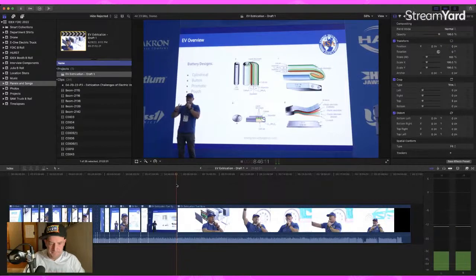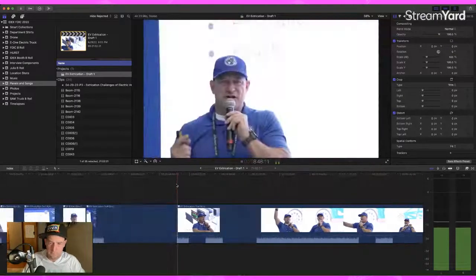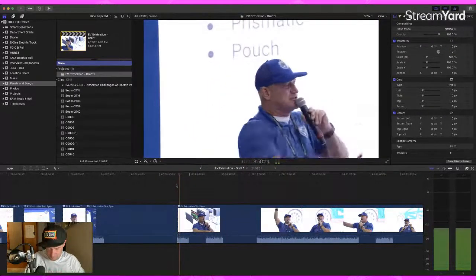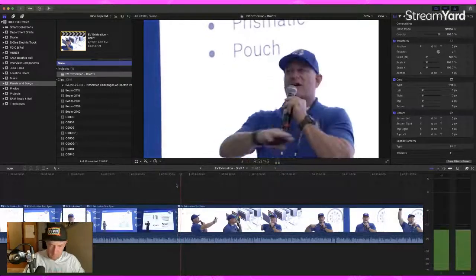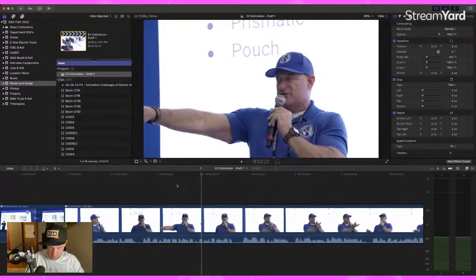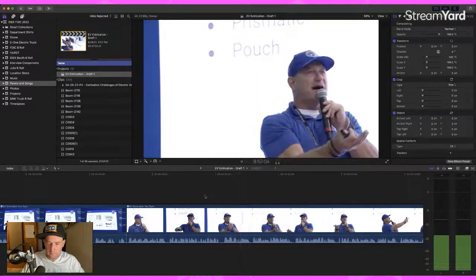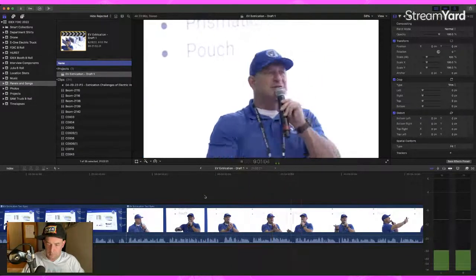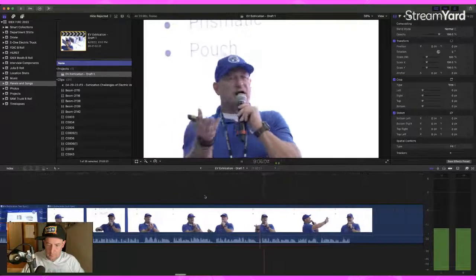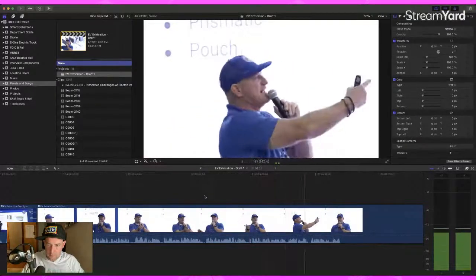On one vehicle, okay? So what you need to understand is you may have cylindrical cells in your traction battery pack, or the battery pack is built in the floor pan of the vehicle. Your low voltage battery on the newer EVs are no longer lead acids. They are moving towards lithium-ion low voltage batteries that are not recognizable as standard lead acid batteries, and many of those have prismatic lithium-ion batteries in them.